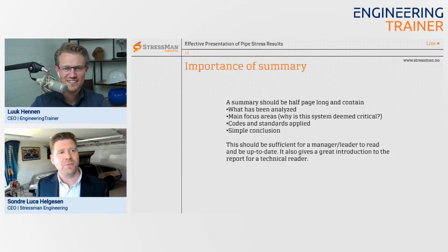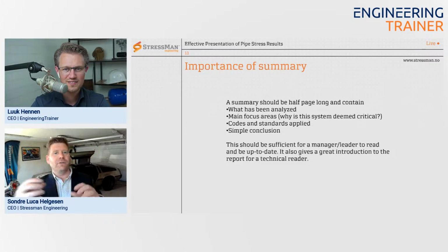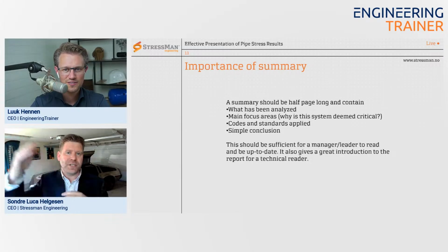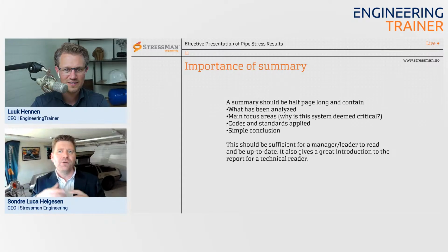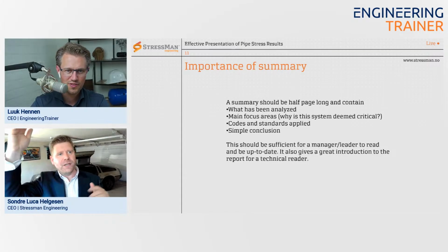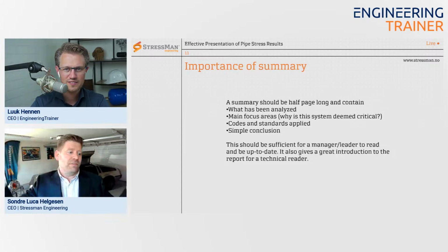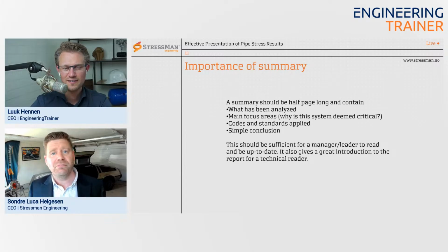So that could be a judgment call as well. We do that several times on offshore rigs where it's limited with information, and we're just going to insert, for example, a T, and then we're going to have some equipment connected to it. So not really going to impose much loading or stiffness change to the overall system, running the system part that we can see and we have data on. Then we cut it out and put in the T, and we say, okay, results changed a percentage, 1%, 2%, and then it's like, yeah, this is not going to change drastically the behavior of the piping system.